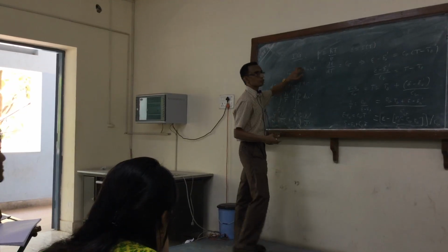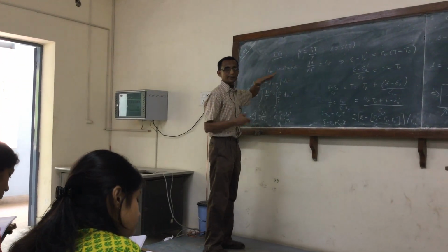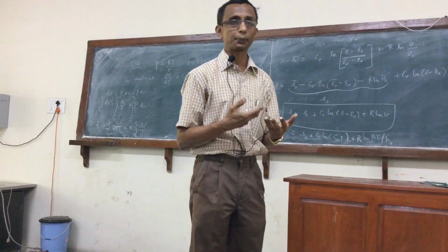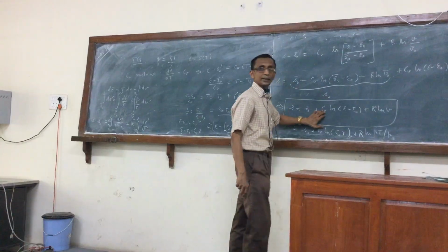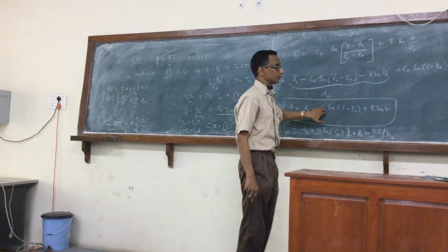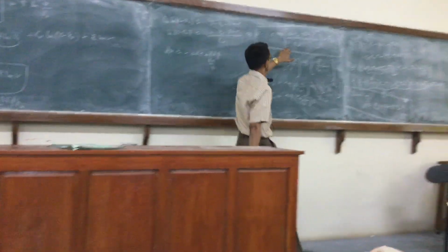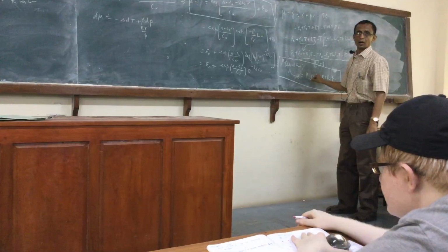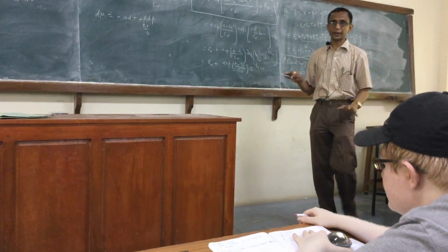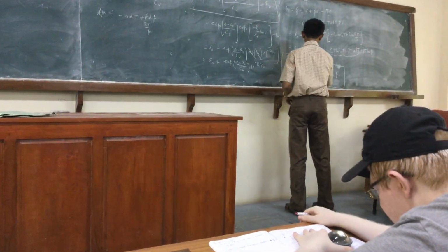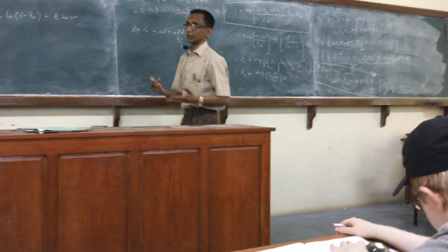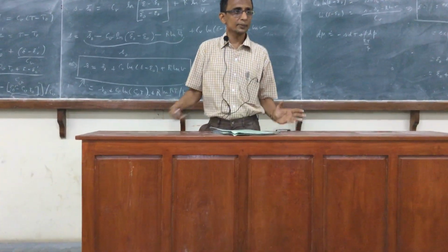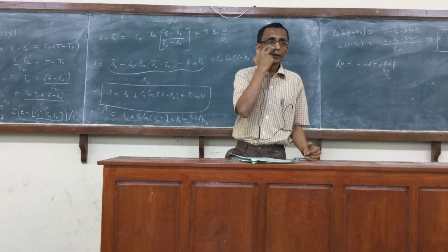So if I choose a constant Cv ideal gas, clearly the Cv of one ideal gas will be different from the Cv of another ideal gas. So that is the point that distinguishes. That appears here. Right, the Cv, in this fundamental equation, it also appears here. And here, for instance, when you just leave it like this, this is the common form that all ideal gases have. Clearly, this function of temperature will vary from one ideal gas to another. You have to keep that in mind. These are some standard properties of the ideal gases.